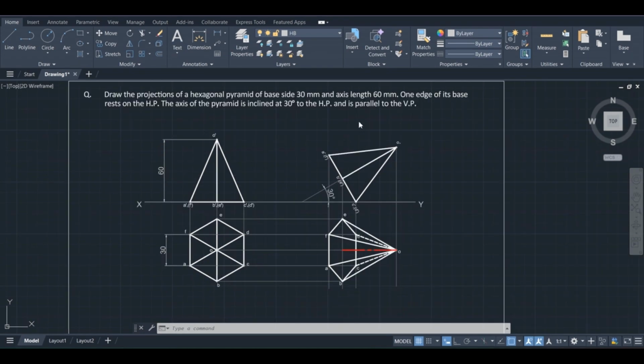In the top view, when we are watching this from the top, points C and D are not visible. The CD is an edge that is on the ground, means on the horizontal plane. So CD edge also invisible. That also the edges connecting BC and DE. So these two edges also are invisible while observing from the top. So we have to make this CD and DE, of course BC also, into hidden.